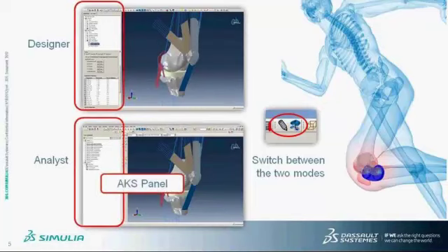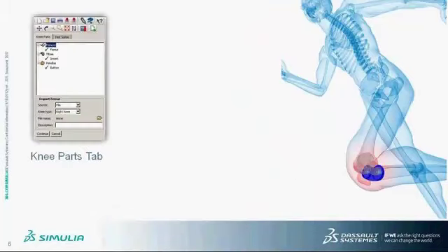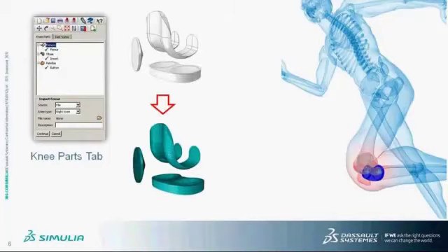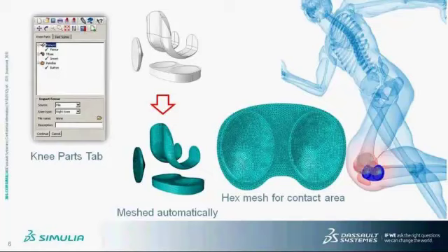For both modes, the Abaqus Knee Simulator functionalities are collected in the AKS panel that appears on the left of the interface. Within the AKS panel, there are two tabs. First is the Knee Parts tab. In this part, the knee implant components are imported into the Abaqus Knee Simulator. These components are mapped automatically upon import. And specifically for the insert polymer parts, to ensure accurate contact pressure calculation, we provide a semi-automated hexahedral mesh for the contact area.